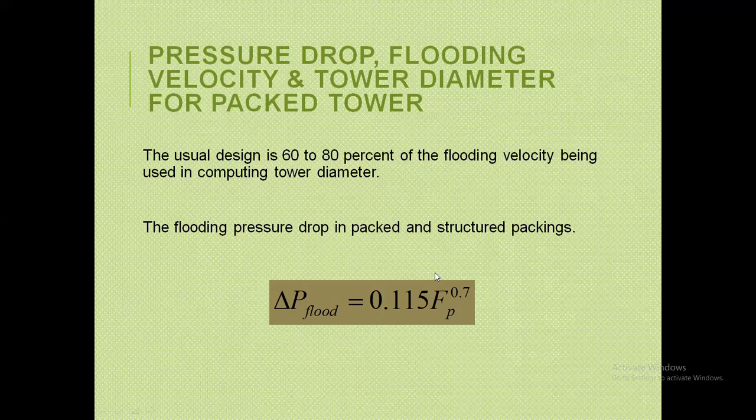Knowing the packing factor will tell you the corresponding pressure drop in your tower at the condition when it is said to be flooding. Now, what is this flooding condition? It is a condition, class, in your tower wherein your solvent that needs to leave your column at the bottom, the solvent that carries with it the solute, or the contaminant in your gas mixture, does not do so. Remember, your solvent is introduced on top, so it flows down, and it should be discharged at the bottom of the column. During flooding, this does not occur. Instead of going down to the bottom of the column, it goes up together with the gas. So both the liquid and the gas leave at the top of the column, and that's a condition we call flooding.